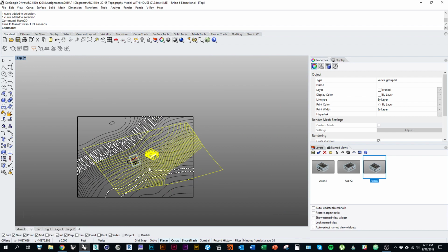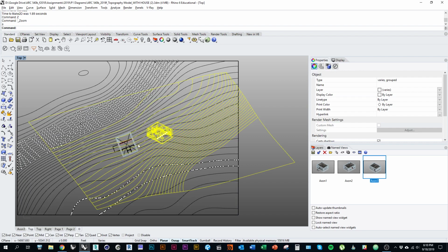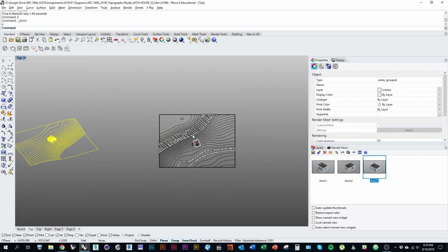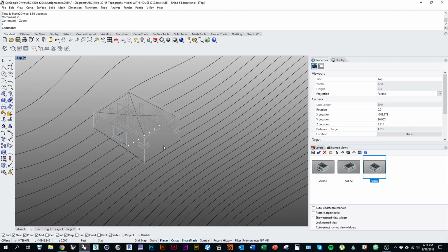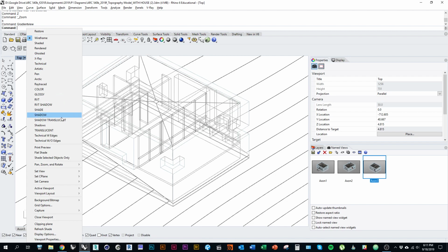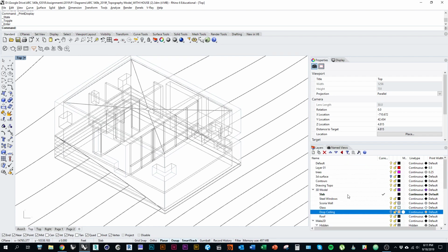Before I deselect anything, I want to make sure I can zoom, Z enter, selected, S enter, to zoom to wherever my drawing might be. Then I'll move it out of the way of any existing model or drawing that might be in the same place. Okay, now I'm also going to turn off my background gradient view, so I can see my line work a little more clearly. And in the viewport options, you could toggle into print preview, just so you can more clearly tell what these lines might be doing.